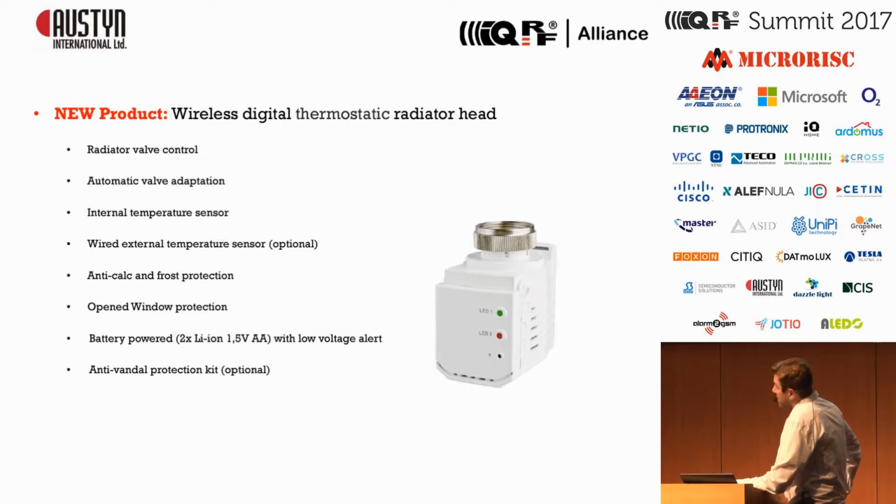And in the end, this is our new product. This is a wireless digital thermostatic radiator head. It will be a product for administrative buildings, to control the radiator valve with automatic valve adaptation. It means you can adapt the head to several types of valve to set the effective stroke of the valve, and this ensures it works properly with this head.